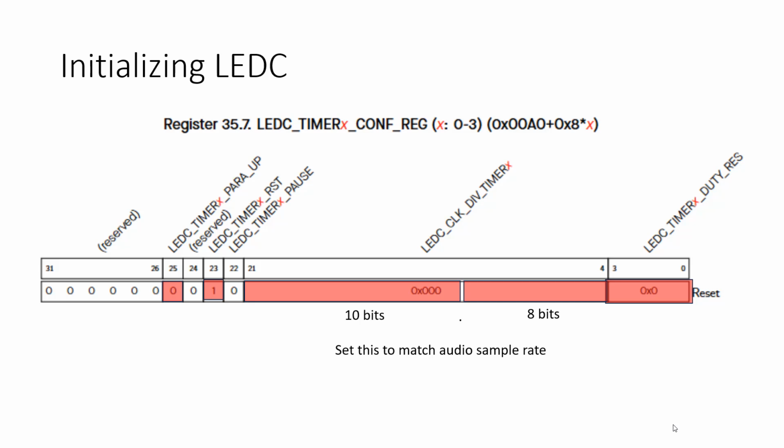And so in other words, you can calculate the whole part by doing your division, 80 megahertz divided by the sample rate for your file, and just rounding it down, right? If you round down the division, that's the whole part. And then the fractional part, you can calculate by isolating the fractional part and multiplying it by 256, right? Because there's 8 bits here. So what we're showing is this is in units of 1 over 256, right? If you treat this like a separate field, it's how many 1 over 256 are part of your fractional number.